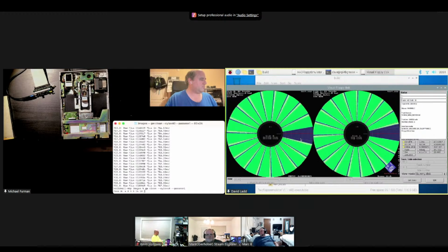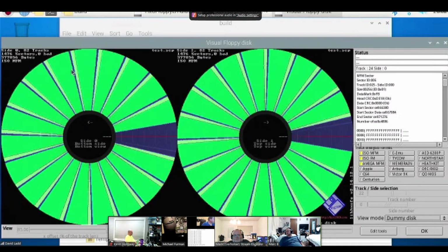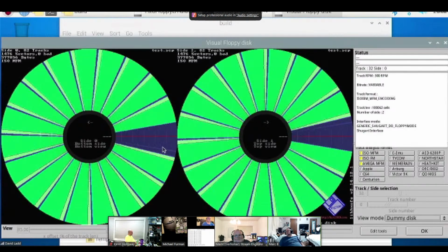If you look at my screen over here, I've got what would be a blank OS9 floppy disk on a 3.5-inch drive for CoCo. Look, there's almost a whole sector's worth of space free. Now, as Mikey was discussing, if you look at either the FM or the MFM encoding, this area actually is data, but it's not data that's read as a sector. It's data that's written as a part of the track. And its value, I think, is 4E hex.